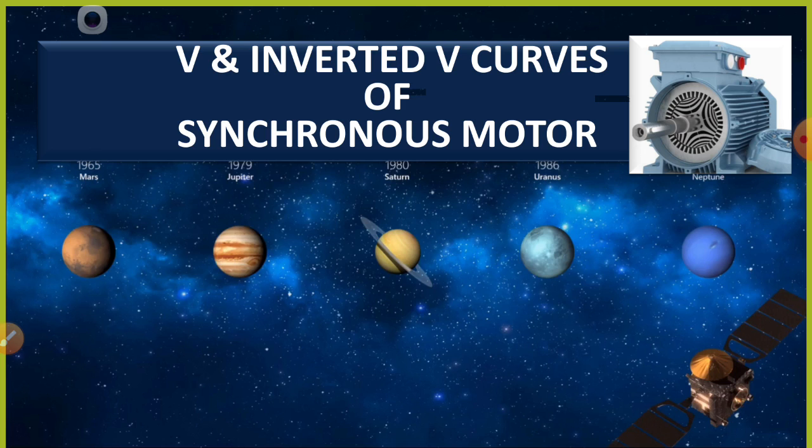We also assume that if the resistance of the armature is very low as compared to the armature reactance, then we simplify the mechanical power developed in the motor: PM is equal to back EMF voltage divided by XA into sin alpha. Based on these simple applications, we have calculated a few problems.